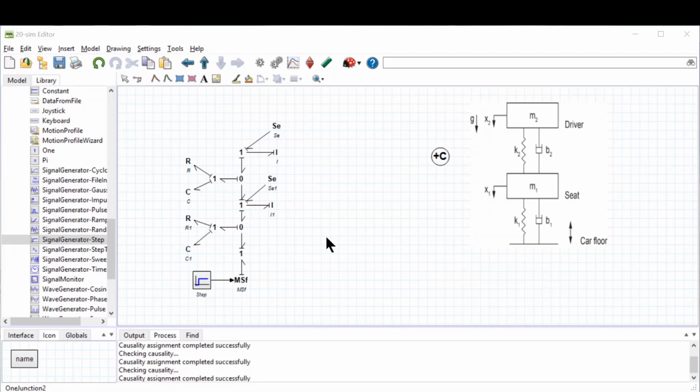This is a very important part of bond graphs, but one of the advantages of this tool is that it is automatically assigned. If you see for your model that one of your causality strokes is not in black or the same color as the rest of them, usually it comes in green or some color close to red, therefore you don't have integral causality for that bond graph. It's not the end of the world, but we have discussed in the text that it could be an algebraic loop or derivative causality, and you will get a message underneath here.